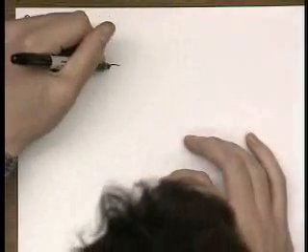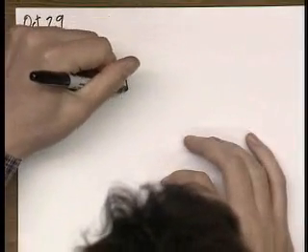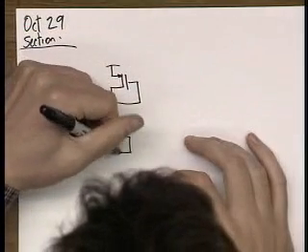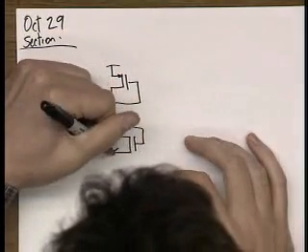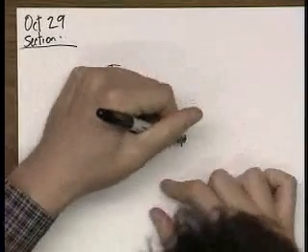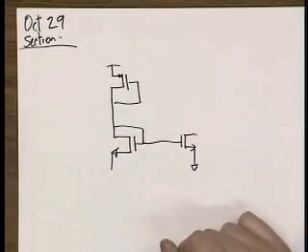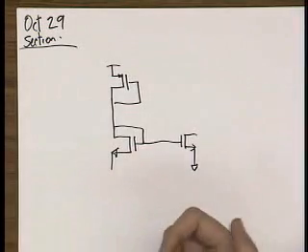Now, if we can go back to the overhead, what a lot of people did for their bias circuit is some variation of this, to generate their bias current: some number of back-to-back diodes. It might have been stacked diodes, whatever.